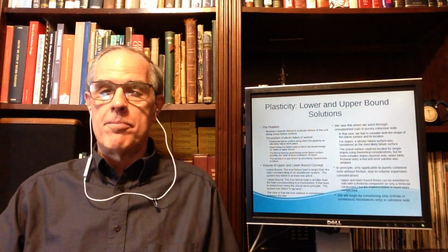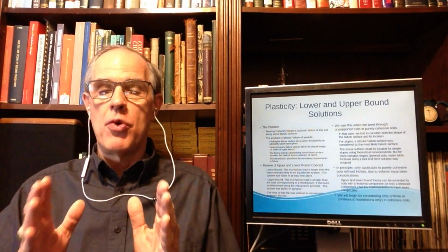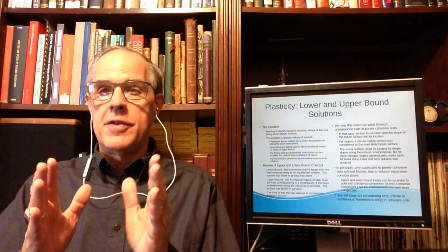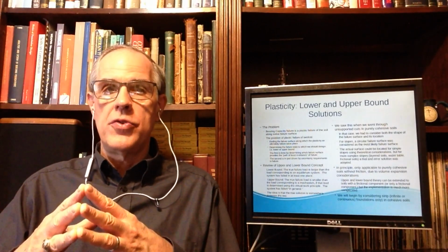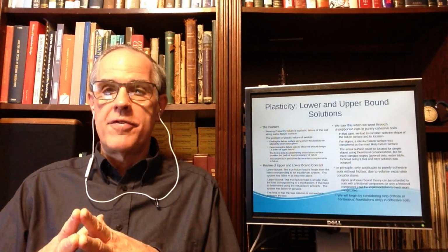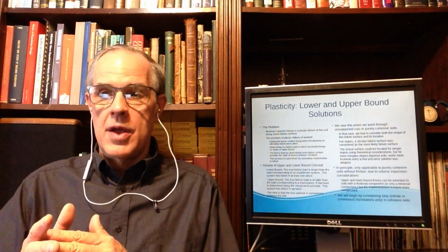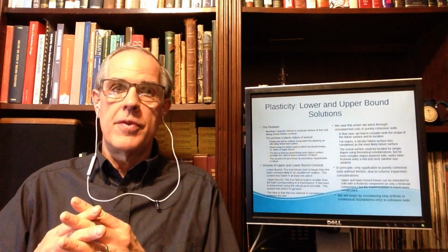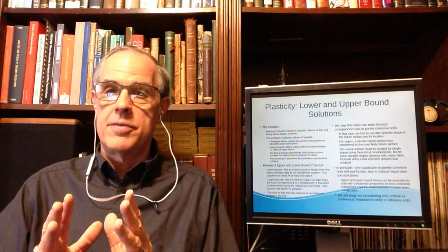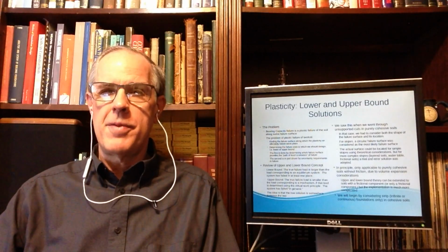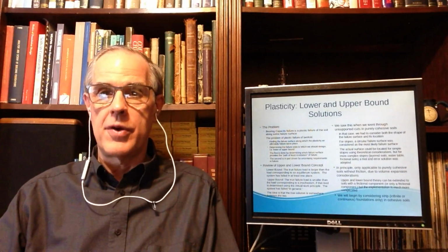The use of lower and upper bound brackets those two points and says that the real failure is somewhere between. We talked about, if you remember, the N factors we used in the slope charts. They can vary; the brackets were between 2 and 4 for those, but in reality they could vary somewhere in the middle. And that was 2 and 4 for vertical cuts, obviously, if you've got a slope cut that goes down. Well, that little bit of review is pretty much the bracketing procedure we use for lower and upper bound.